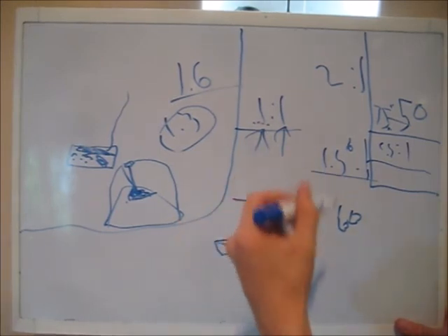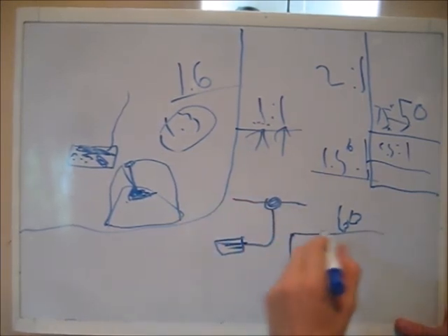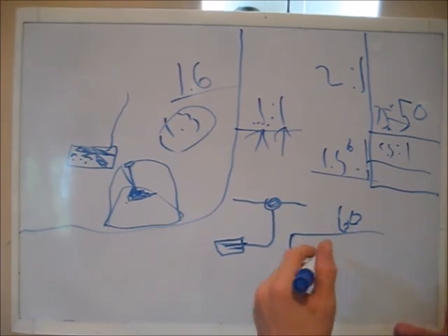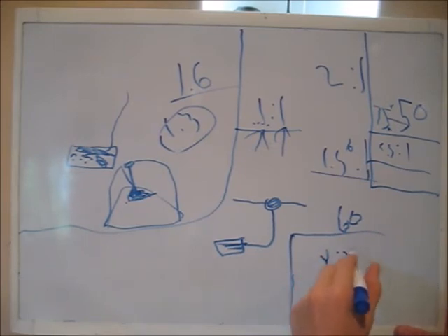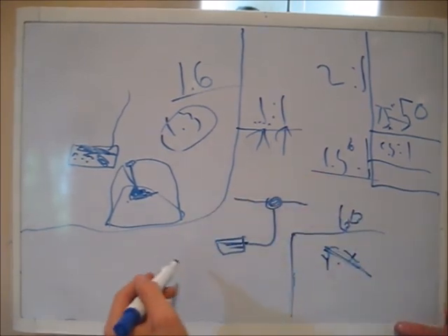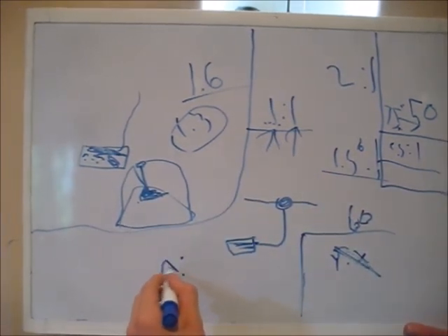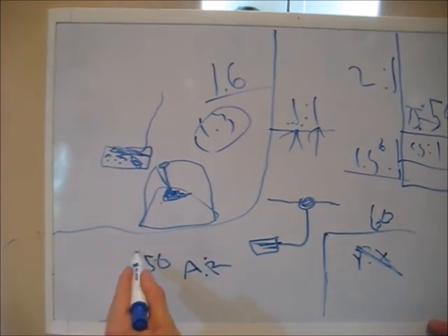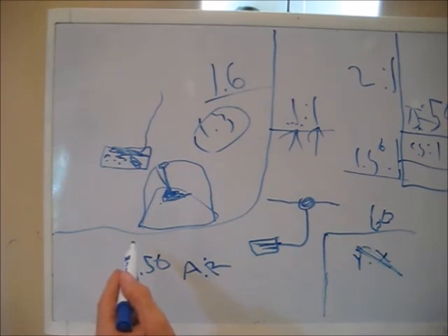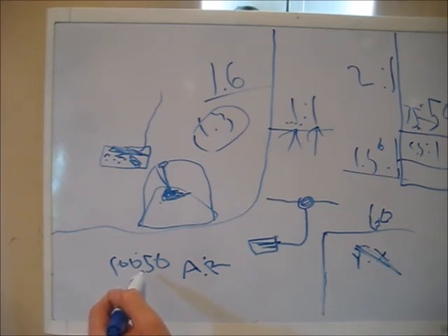So as long as you have some math or some scratch paper or a calculator handy, you can instantly figure out what the impedance of your antenna is based on this number. So if I say, okay, I have a 2-to-1 SWR, let's just make this a little easier to understand. Point A and point R. Point A is your antenna ohmage, and point R is your radio ohmage. We know that R is always going to be 50 ohms. So we can deduce from a 2-to-1 SWR that this is 2 times that, which lets us know that our antenna has a 100 ohm impedance.